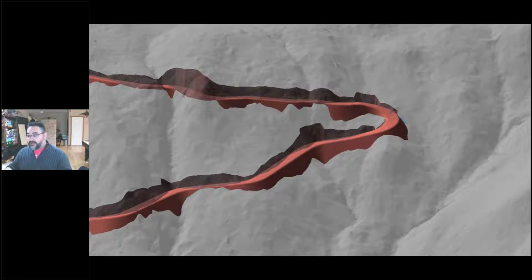And this is typical the kind of road scenario for us on the west coast of North America, where we have steeper ground. And we're climbing up from the bottom of the stream there with our road, following the contour. And then we have to change directions. Well, where we change direction, we call that a switchback here, where we want to change those directions on the flattest spot that we can find on the hillside. And almost always that is on a ridge, and the ridge is often between two water courses. So we change directions on that ridge and keep heading up the hill.